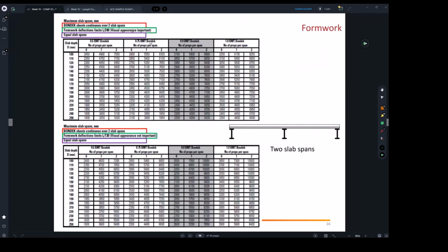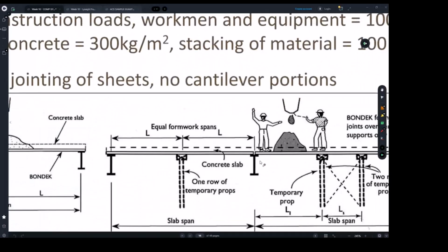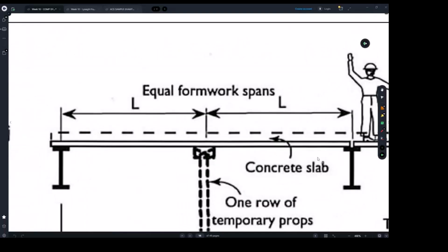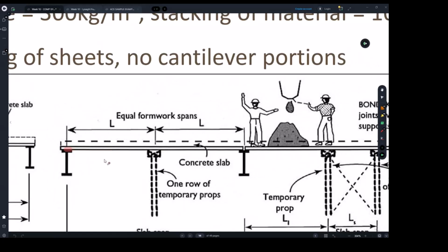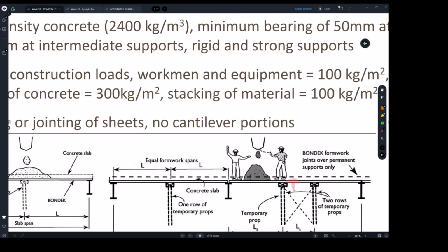You have the band beams. Usually in construction, like this one as well, if I pay attention here, you see there's a gap. So it was decided to have it as simply supported. If we had another steel beam here in the middle, then this bonding will be continuous over 2 spans. If your metal sheet stops and starts, then it's not continuous.